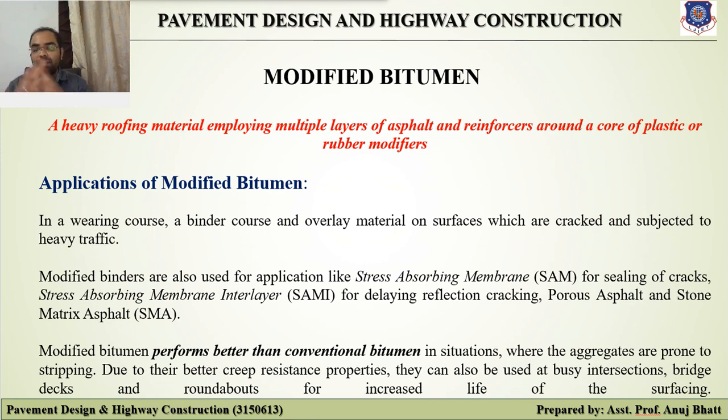If we talk about the application of modified bitumen, a bituminous mix prepared with a modified bitumen has a higher stiffness modulus, enhanced fatigue life, better resistance to creep, and higher indirect tensile strength. It is suitable as a wearing course, binder course, and overlay material on surfaces which are subjected to heavy traffic.